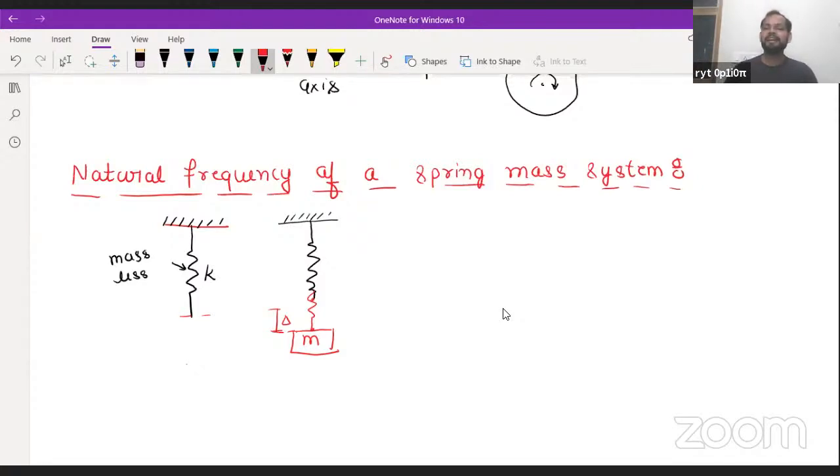For example, there is a beam, and you are applying a force at the end. So what will be the deflection? In that case, there is a permanent type of deflection, that is nothing but delta is equal to FL cubed by 3EI. So corresponding to that force, the system will acquire a new position, and at that position the system is in equilibrium.